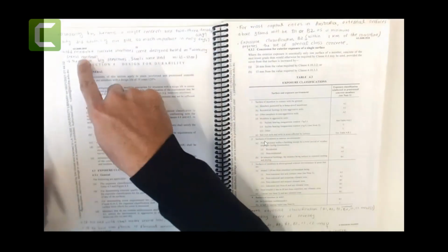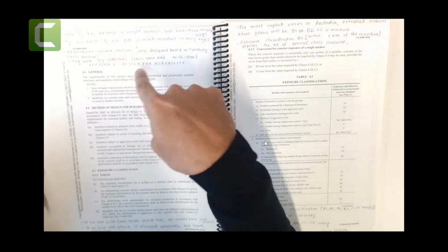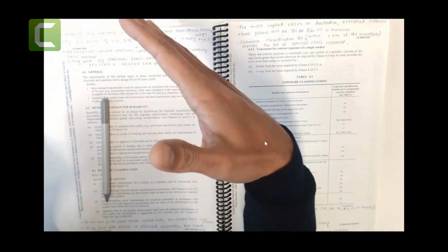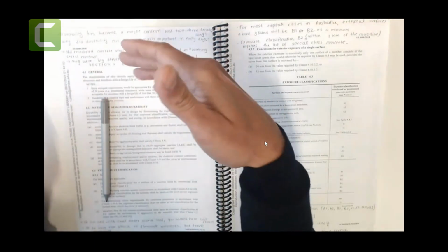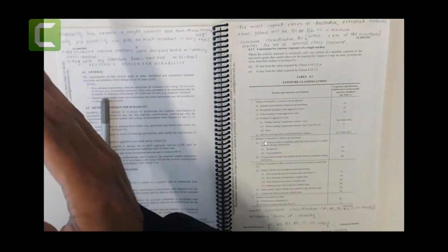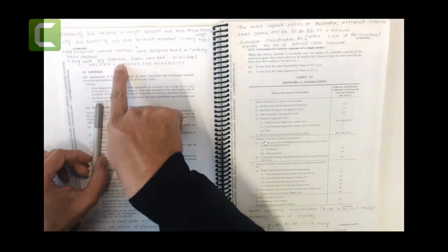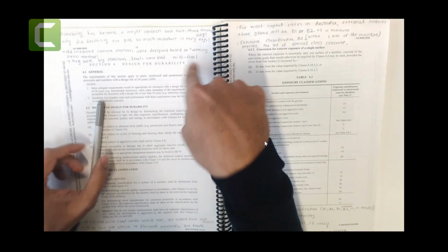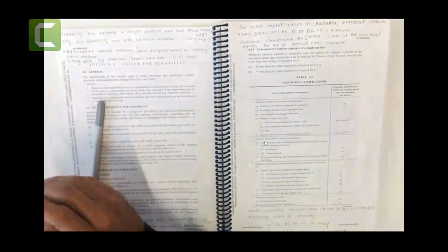In early days, in old structures, you have seen, even in Bendigo, there are many old buildings, right? They were designed based on the working stress method, meaning that they are bulky. You can see the size of the columns, beams, and slabs is huge, and the working stress method doesn't consider plasticity and all sorts of things. So they are big structures, and the steel used was mild steel, soft, 250 megapascal.